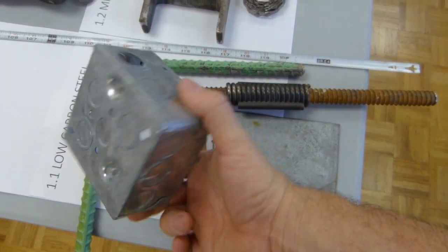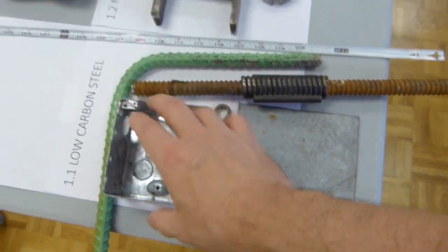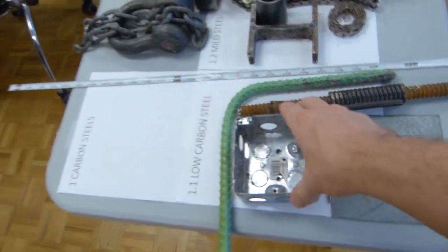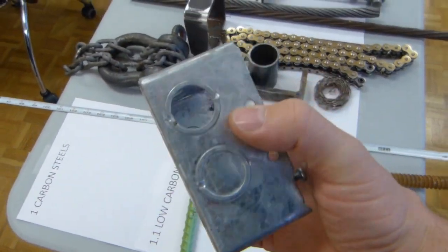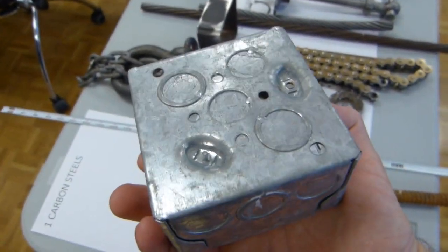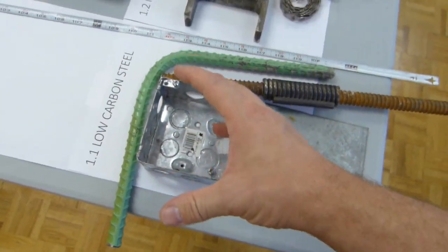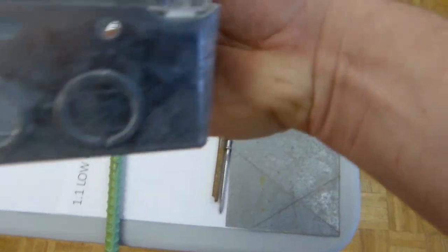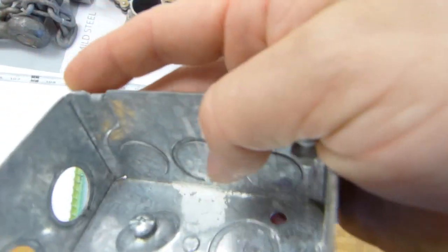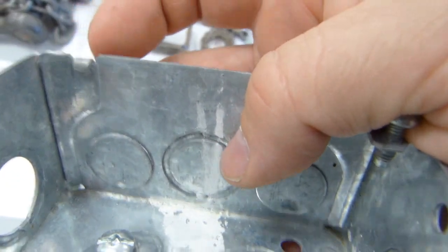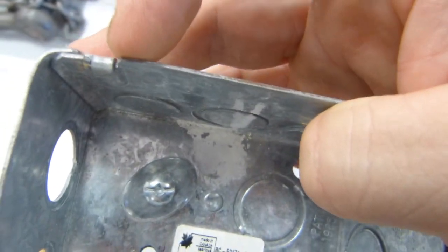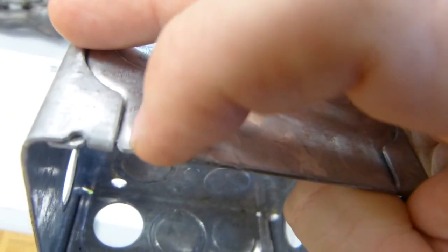Here is one manufactured example. This is a duplex outlet for the electricians, something like that. That's behind the faceplate. There is this box, and this is where you can do your wiring connections. You can see that there are circular holes punched through it. This is how it's manufactured. It's made by punching, so the shapes are crimped. You can see such crimping over here. There you can see metal folded over onto itself to join the sides of the box.